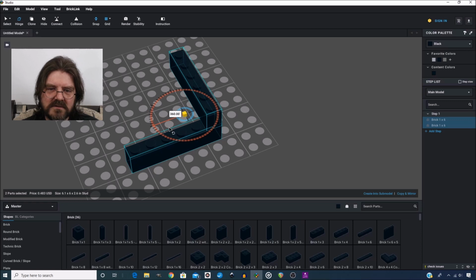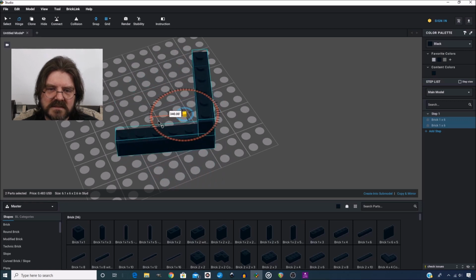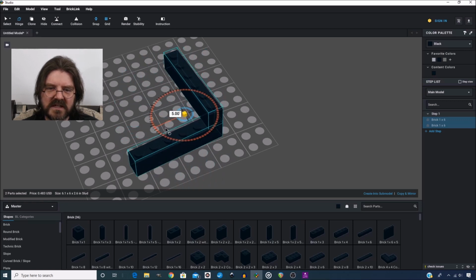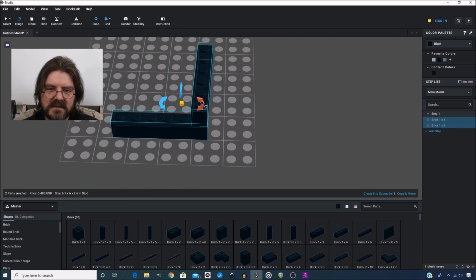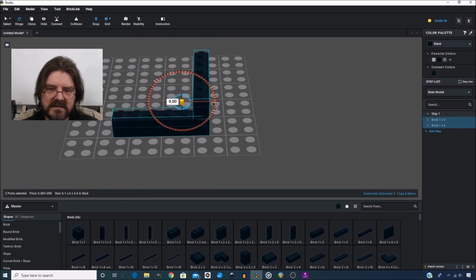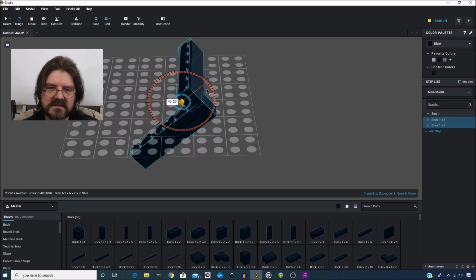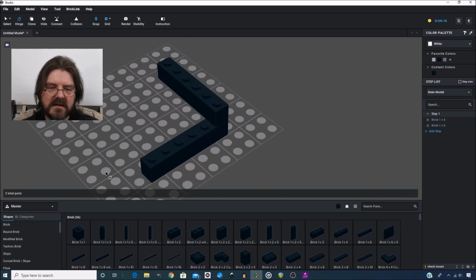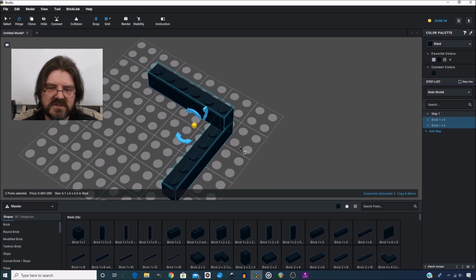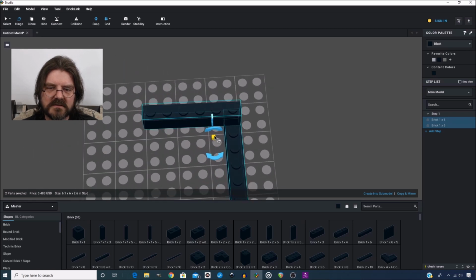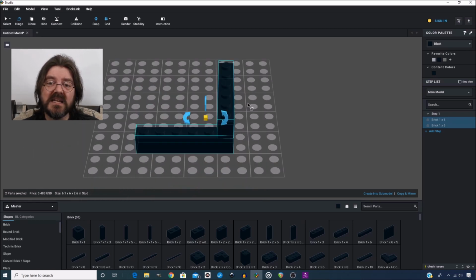Grab the side arrow, that lets us tilt it horizontally, and this arrow is vertically. Again, notice that this is showing where the hinge point is. I should mention, if you are in any of these tools, the easiest way to go back to a regular cursor is just by pressing the V key.